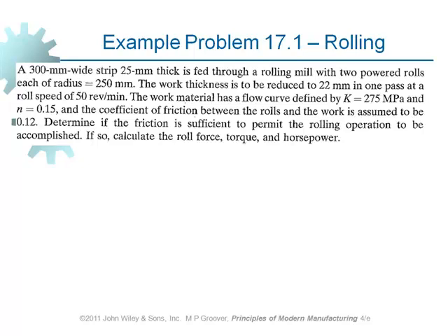Indeed, the rolls do play two roles. They pull material into the gap between the two rolls. And what makes that possible? Friction between the roll and also the sheet metal. If there is sufficient friction, then rolls can pull the material in the gap between the two. If there is less friction than required, it does not happen.